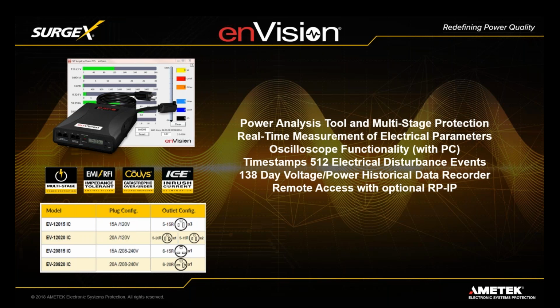So, what does this mean to you? This allows the techs to pull up power reports in real time and prove to the clients that issues such as power outages or voltage fluctuations have occurred and that it's not your equipment that's the issue. It's a great tool for getting that monkey off your back when it's not really your equipment that's the issue. It's also a great tool for specifying UPSs. You can measure the current draw or the power draw of an entire rack or a piece of equipment and make sure you are sizing your UPS correctly.